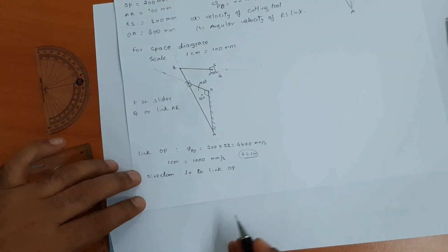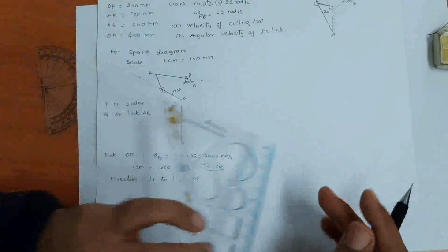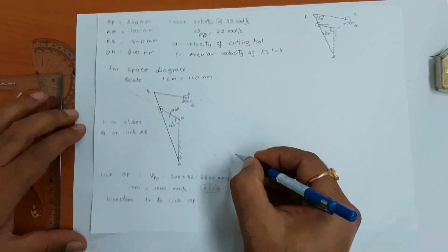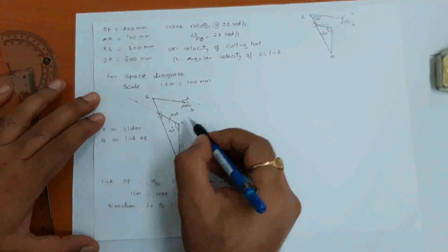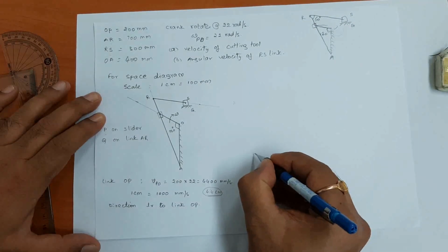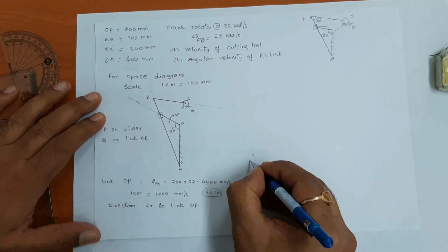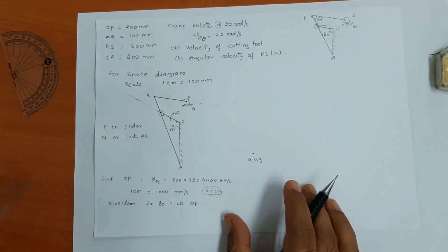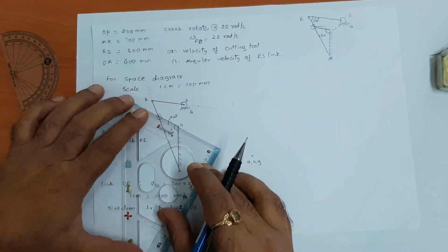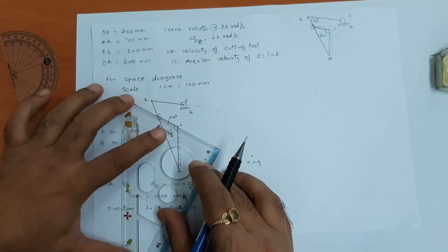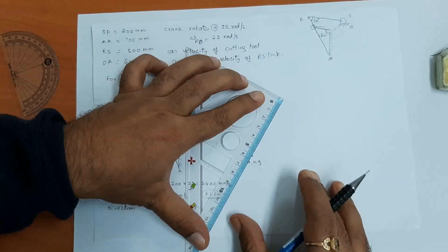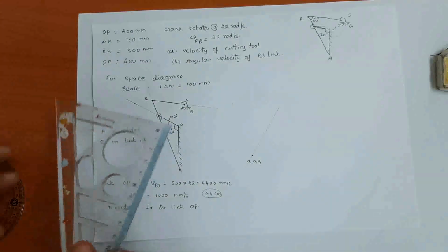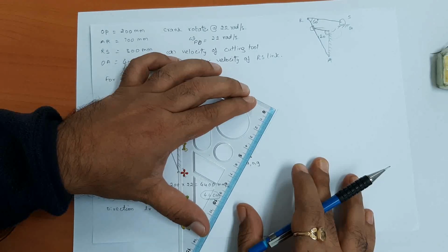Okay, we know that. So now we will try to draw the velocity diagram. So here to draw this, how many fixed points are here? Actually A, O and G, there are 3 fixed points. So we will take them as 1 point with small letters a, o and g. Okay, so now we will draw a perpendicular line to link OP starting from o of the magnitude 4.4. First I am drawing like a thin line. Okay, I am just marking 4.4.